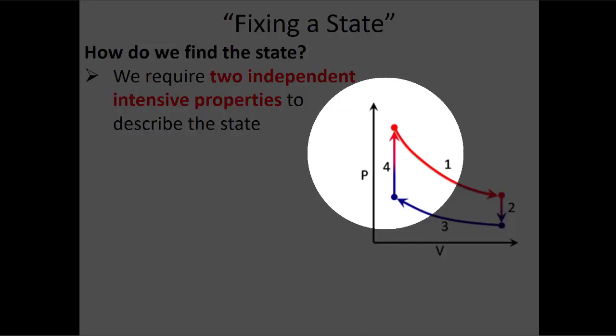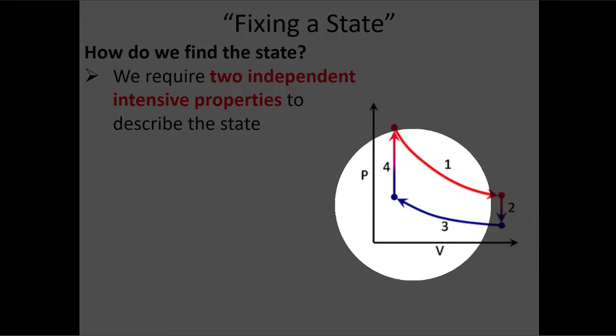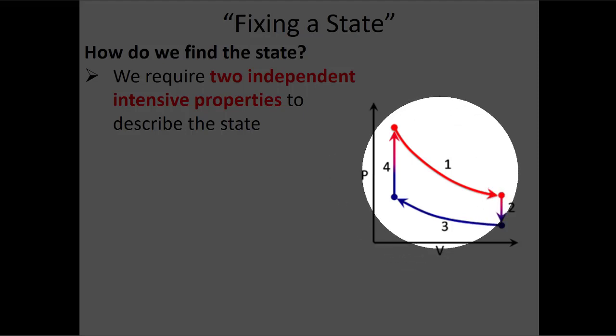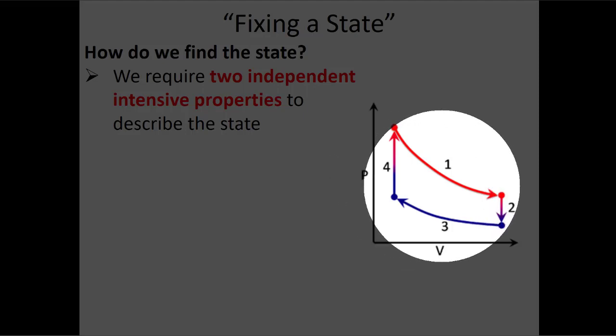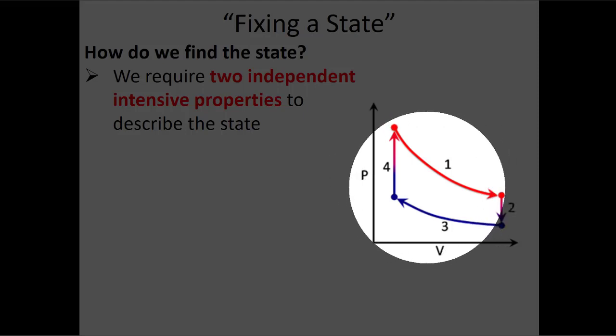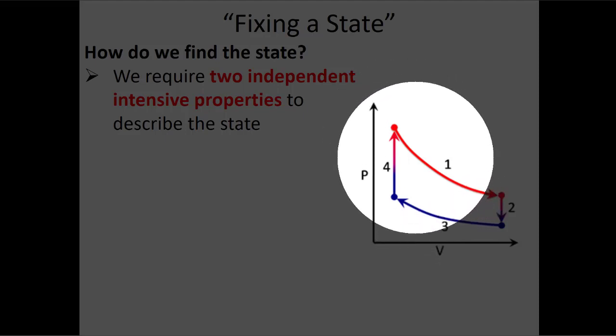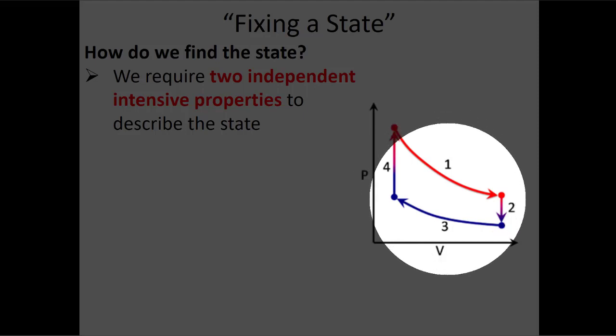We've talked a little bit about drawing these PV diagrams to look at processes. Now, the points are state points, and my processes are the arrows. So as I look at this first process, as I go up here, my pressure is decreasing and my volume is increasing.